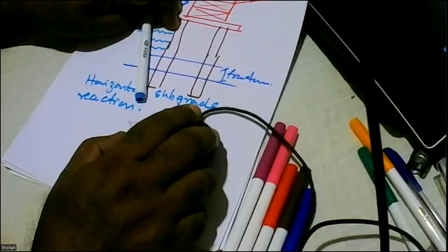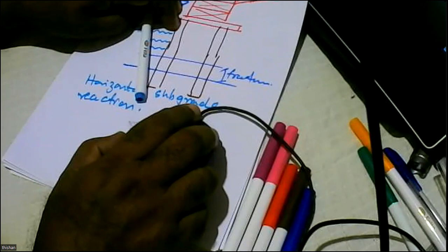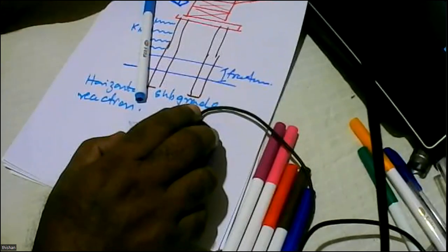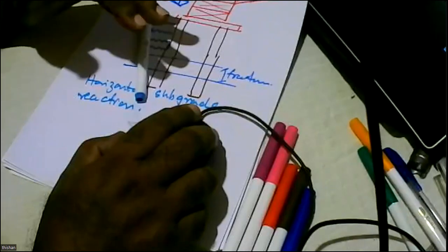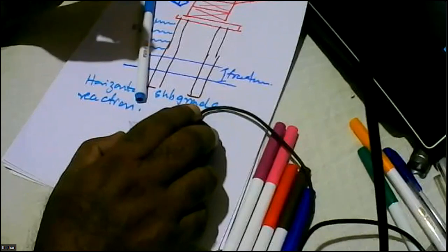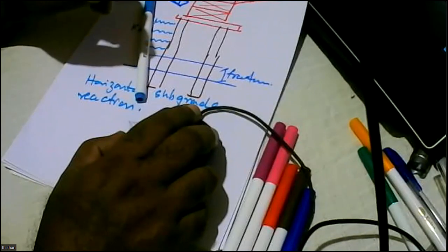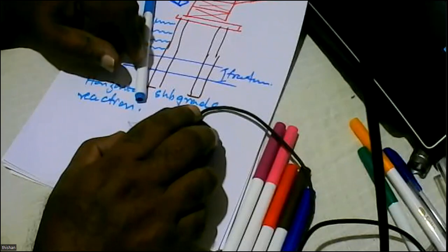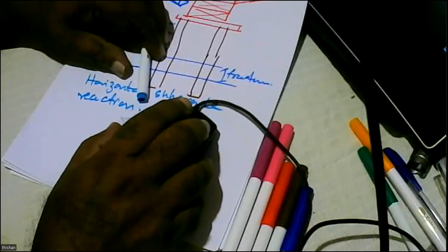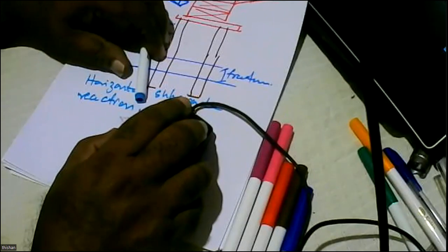That means the water table is high in this area because this is a river. We are considering a bridge. The river is full of water. The water table is high. Though we have good soil having a sand and clay mix, it is going to behave more like a clay soil. So we have to see what type of soil is available.